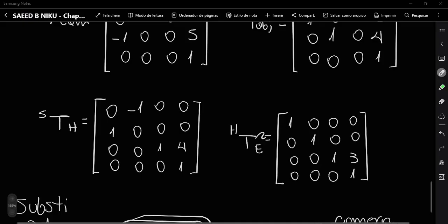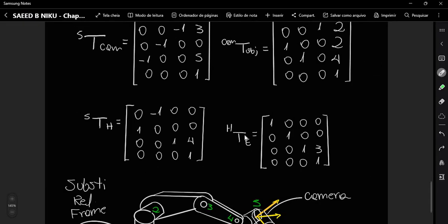The transformation represents the matrix, which contains the information of rotation, and if we are talking about this column, it contains the information of the position or rotation of a certain rigid body, where it is located when we are referencing the fxyz reference system.